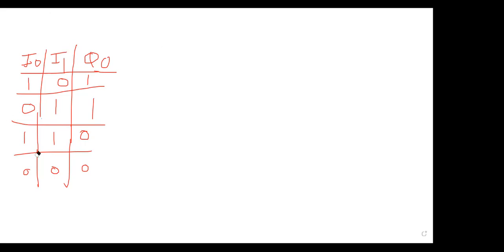As you can see on the screen, you have the XOR truth table. So, inputs, outputs, and conditions. So make a truth table. After that, you start from NO and NC. For a few examples, start from the coil. Start from the coil. It will help you. So make a truth table, go to the first output, and take a coil for it like this. So you can see I did not start from NO and NC. I have taken the coil directly. And I told you, go to the first output.